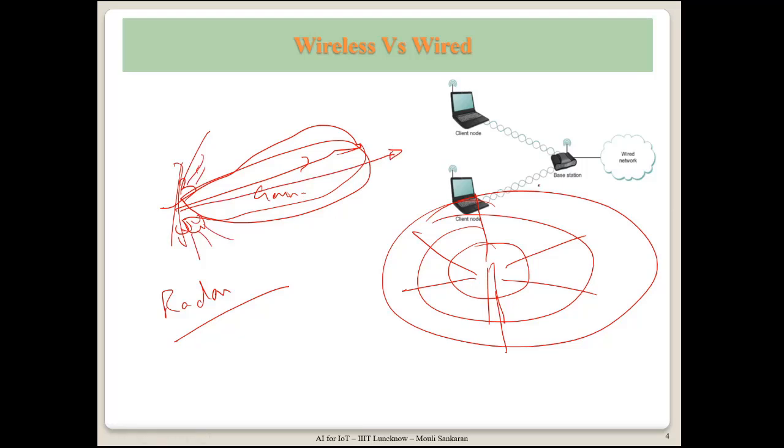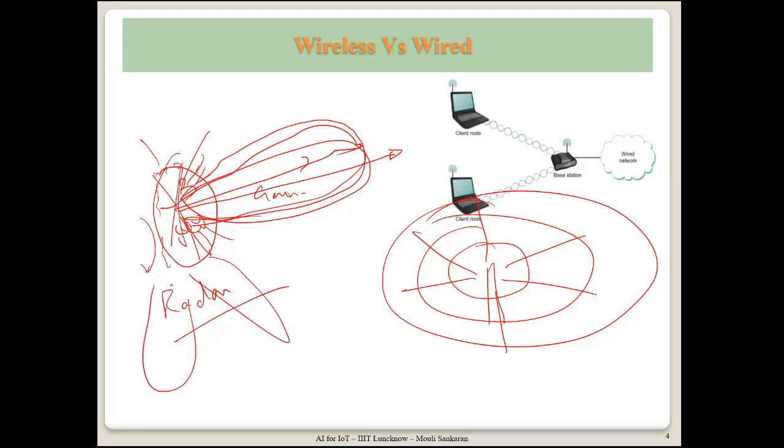That is called a directional antenna. One thing you should understand about antenna is the design of antenna, whatever structure and material and length and dimensions used, decides the radiation pattern of the antenna, and based on the direction it will be changing. So you can keep rotating it, then you will be seeing different angle, different directions.